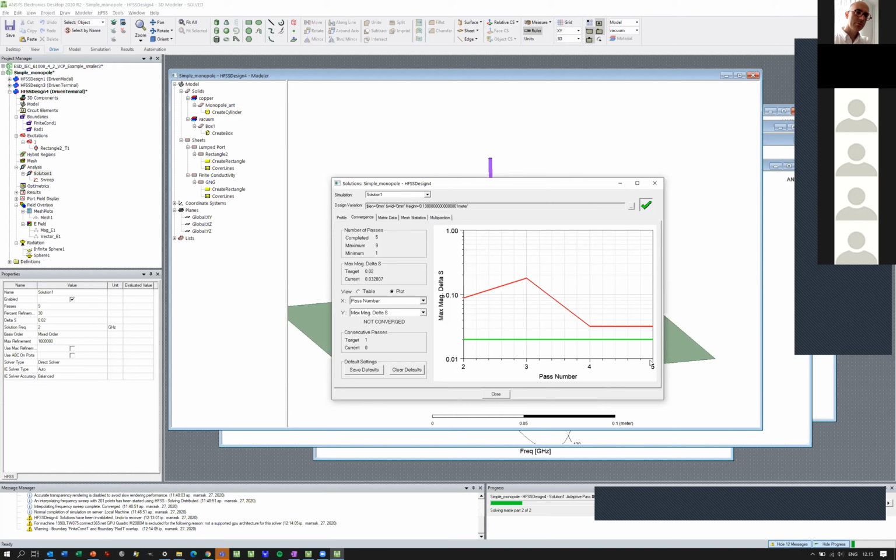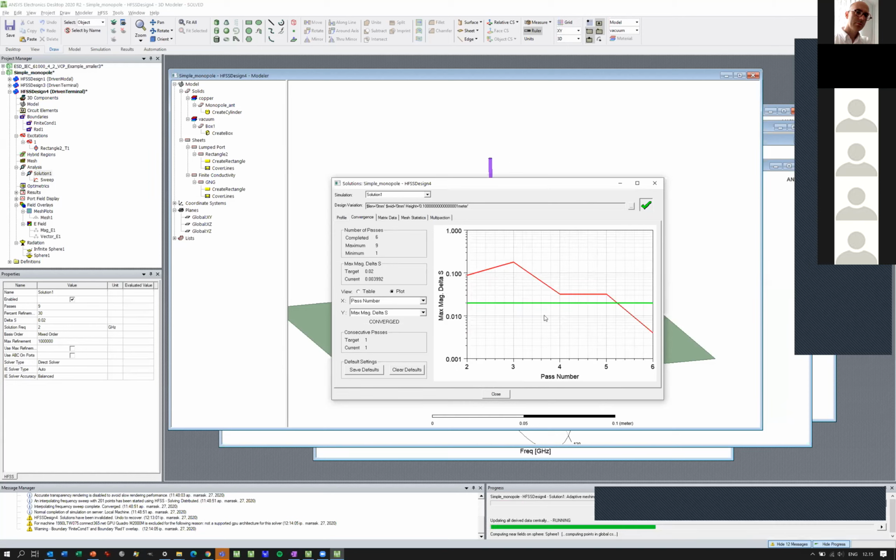And step 6, now it should get the convergence done, yes. And now it will do this frequency sweep and doing the field. Basically, the more calculations you set up for your simulation, the more time it will take. So if I add a far field, near field, or some other mathematics, it will need a little bit of time to do that math when doing the solving.